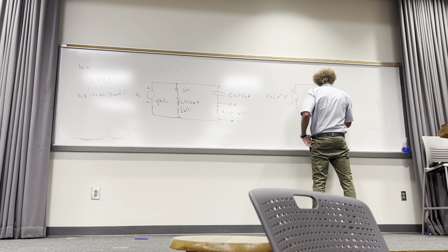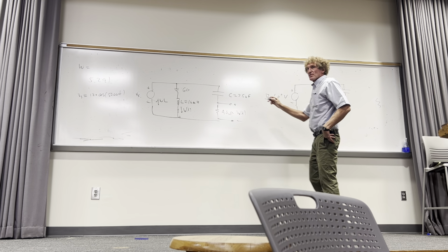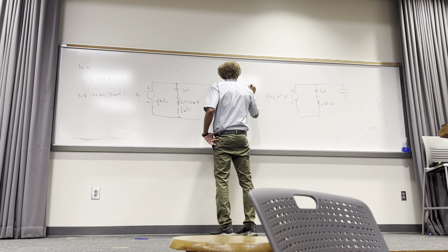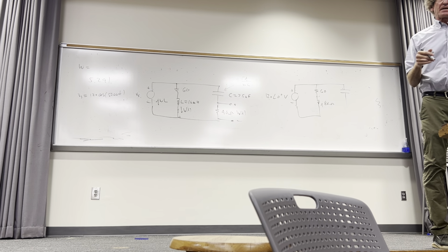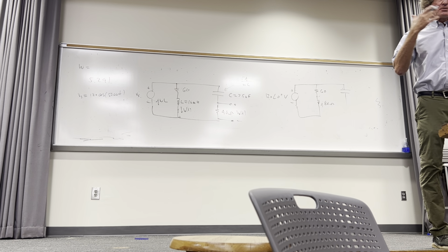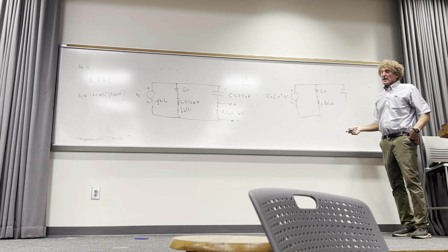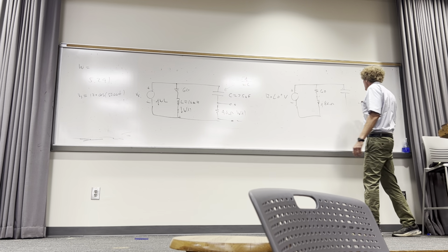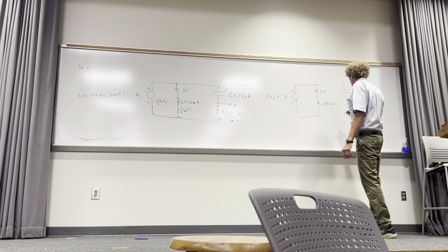80 ohms. Now over here on top, what is the capacitive reactance? It's minus j over omega C. Does everybody follow me on that? How many know that? You're going to need to know it for the exams. I promise you that. They're coming. And the more frequently you use it, the better off you are. So if you take minus j divided by omega C, what do you get? Anyone? 80? Again? All right. And then you have to put 40 down here.